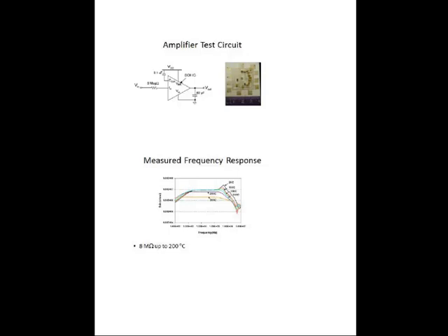And this is the compensation capacitor for the DC voltage level setting. And we use a 3 mega ohm resistance for our measurement. What it does is you basically vary your voltage, and then this node supposedly stays about the same. So you inject the current V over this resistor, and then you know your output, input, and this resistance. You can measure what's going on in your amplifier, basically.